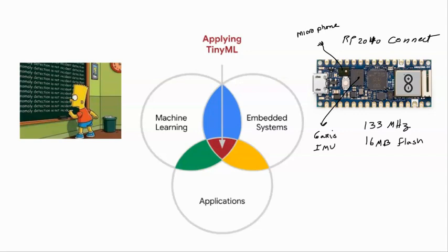Now, one question you may ask yourself is, is any Arduino-based microcontroller suitable for the deployment of machine learning? Now, the answer for this is really not, because you have to look at the computational power, because TinyML models are designed to run efficiently on microcontrollers with limited computational resources. So you need to look at the Arduino boards with microcontrollers that have sufficient processing power and memory to execute your machine learning model.